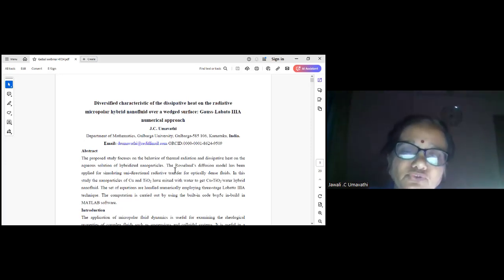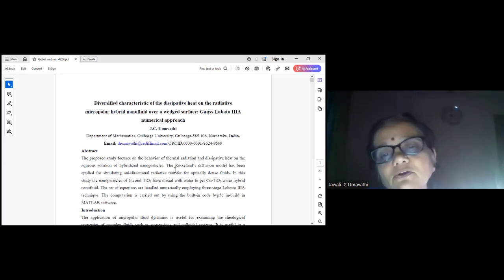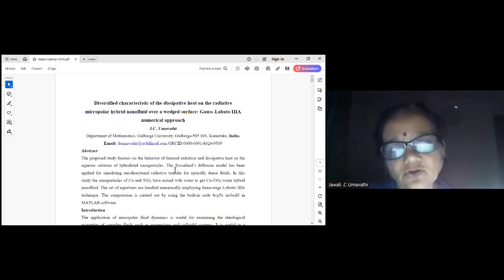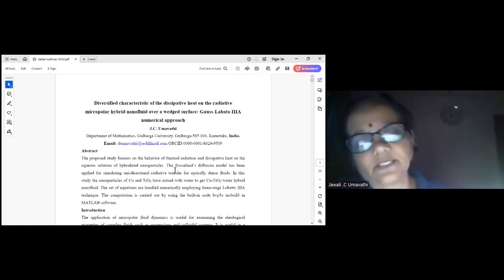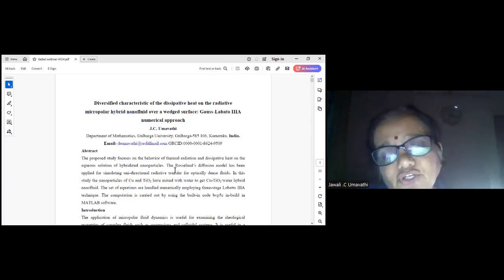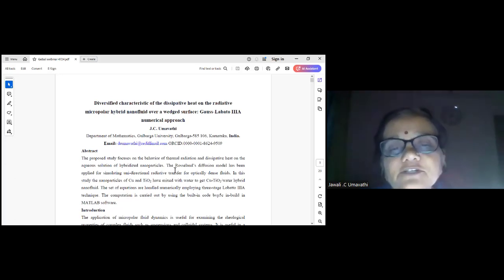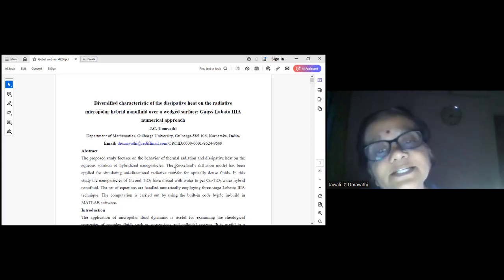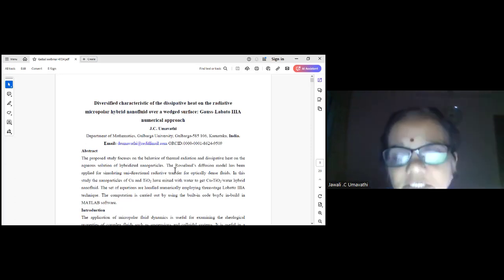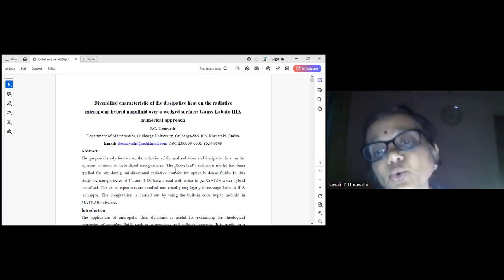But apart from Newtonian fluids, as we know, there are a lot of non-Newtonian fluids. Again, in non-Newtonian fluids, we know very well that you don't have a particular format like how we define a Newtonian fluid. Yes, this is the Navier-Stokes equation for Newtonian fluid. We know the exact relation between stress and strain because it is a linear relationship. So for Newtonian fluids, we have a very good formulation. But for non-Newtonian fluids, it is a non-linear relationship between stress and strain. The word non-linear itself implies that it is unknown for us.